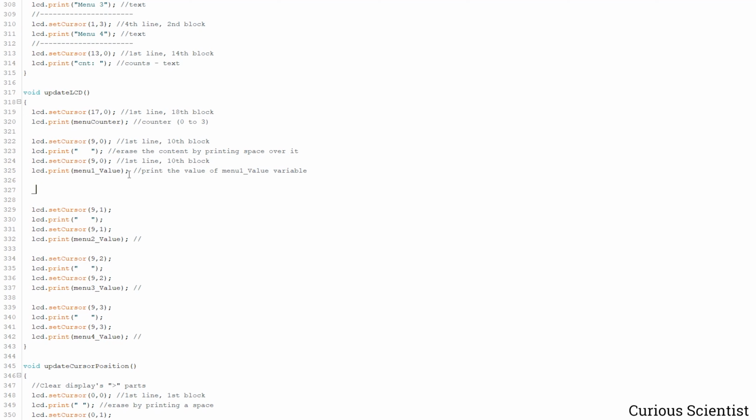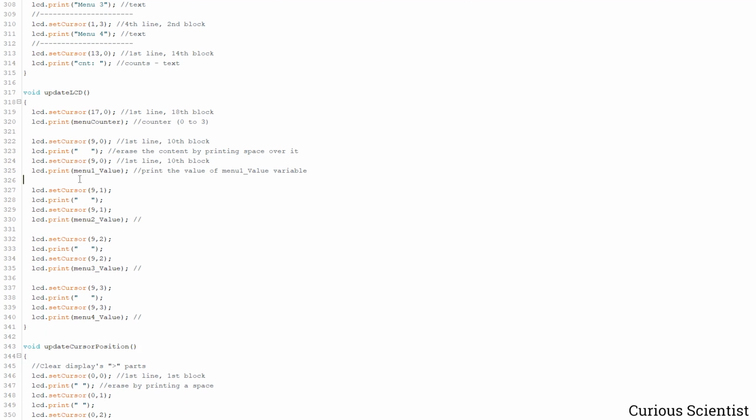However, if you do this kind of operation, and let's say now you have the 10, what happens is that this becomes erased, because here we have 3 spaces. And then we jump back to this position here. So we are here, and enter 9. And that's all. So this is a better way. And if you would do the lcd.clear, that would erase your whole screen. So that's not a good idea.